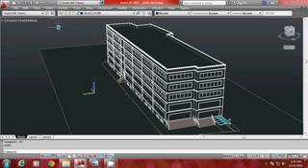You can see that you have one vanishing point over here, one vanishing point here, because when you draw lines along these edges, you can have a vanishing point here, and when you draw lines along these edges, you will have a vanishing point on the right side, and these lines are no longer vertical, they are inclined. So when you produce these edges and when you draw lines, you can find a third vanishing point underneath. So this is a typical example for a 3-point perspective, and this is how you make a 3-point perspective.